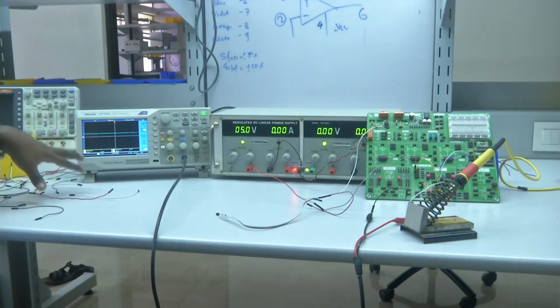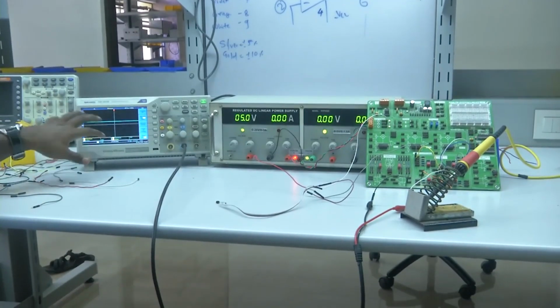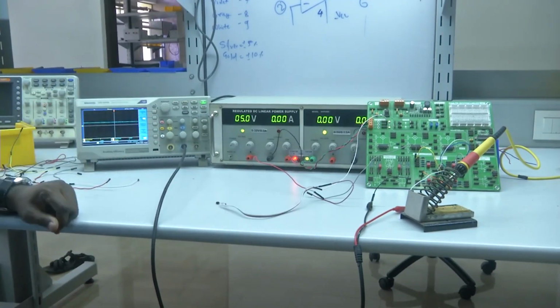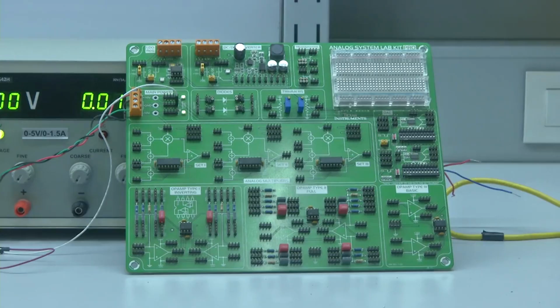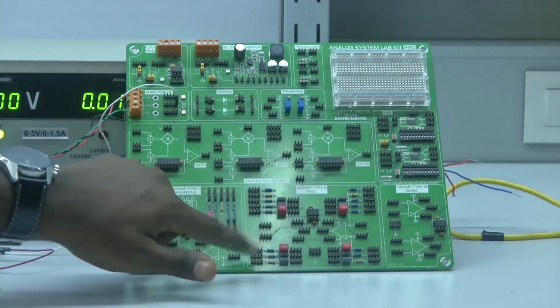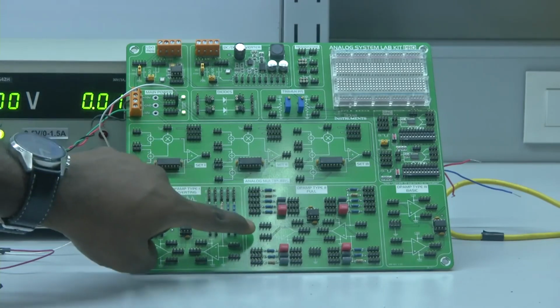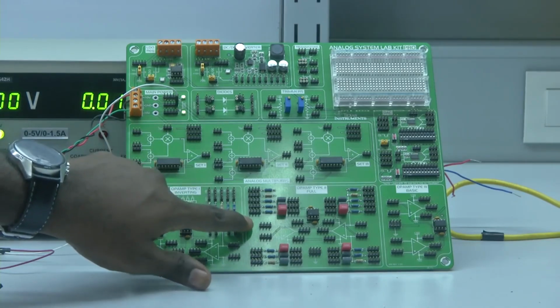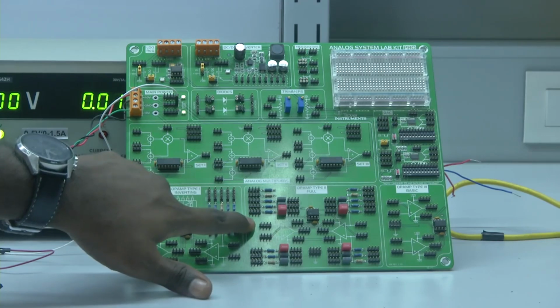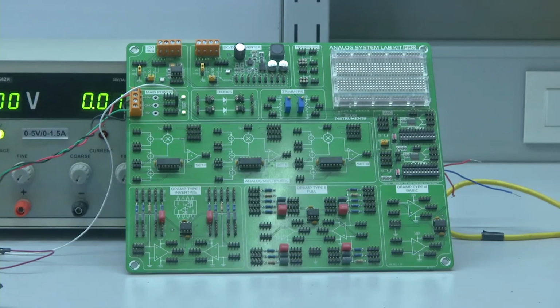Now we will try to realize the same circuit the same way, whatever we have done for the inverting amplifier configuration, we will also try to implement the same by using non-inverting amplifier configuration. Now see how we can implement the non-inverting amplifier configuration at this stage. In case of a non-inverting amplifier configuration, we can use only one operational amplifier where the input should be connected to the positive terminal, and the other end of the input resistance should be connected to the ground.